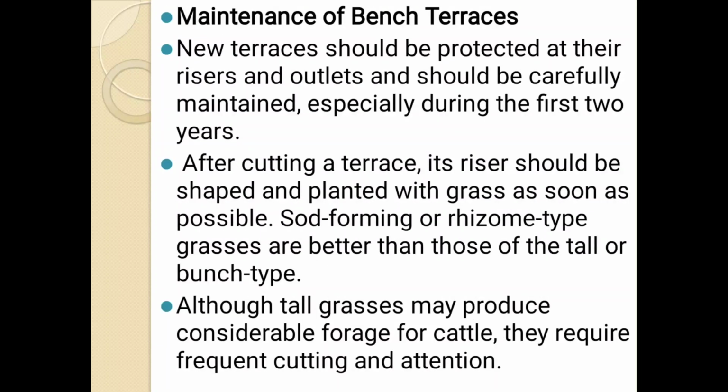Next, the maintenance of bench terrace. While we construct a bench terrace, we have to maintain it at particular time intervals for the betterment of the bench terrace. First, a new terrace should be protected at the riser and outlet and should be carefully maintained, especially during the first 2 years. After cutting a terrace, its riser should be shaped and planted with grass as soon as possible. Short creeping or rhizome type grasses are better than those of tall or bunch type. Although tall grasses may produce considerable forage for cattle, they require frequent cutting and attention.